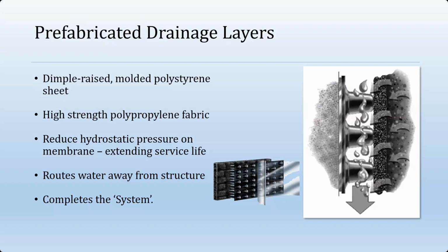A lot of contractors seem to, because this is in a sheet form, if we're using a sheet waterproofing, we're going to apply the sheet waterproofing on the foundation and then place our sheet drainage on top of the waterproofing, and then cover it up with the insulation. And, us as one manufacturer, our details will show the reverse of that. We have the waterproofing on the foundation, we then insulate it, and then we apply the drainage mat on the outboard side of the insulation.